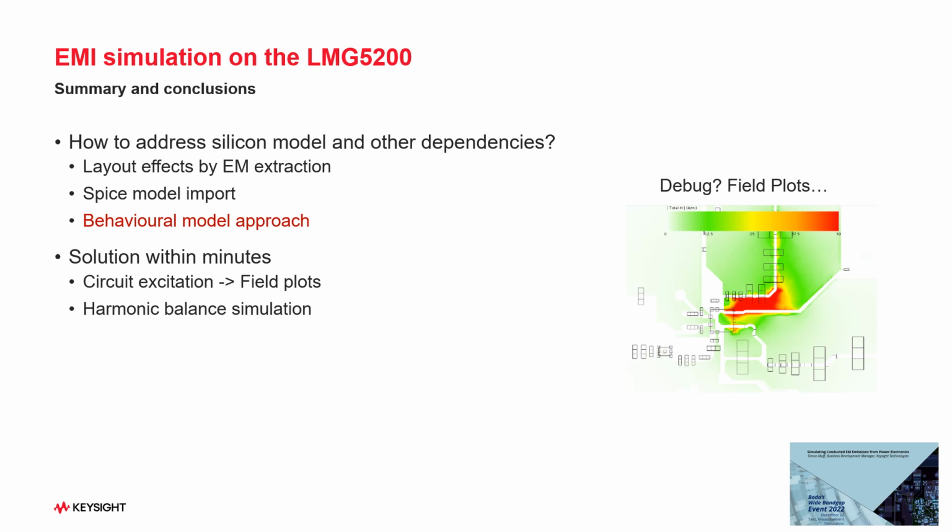So this shown methodology gives you a big advantage versus running an EMC measurement hardware cycle, seeing yourself failing, having to add additional filters and so on, or change the layout. Here you can virtually prove your design very fast before you tape out and build the hardware.